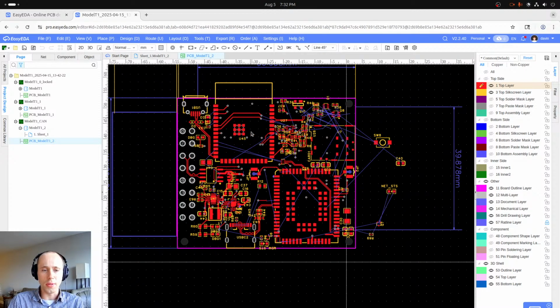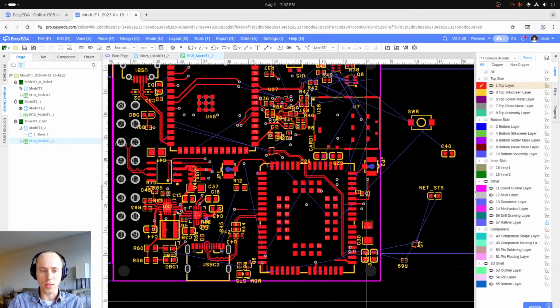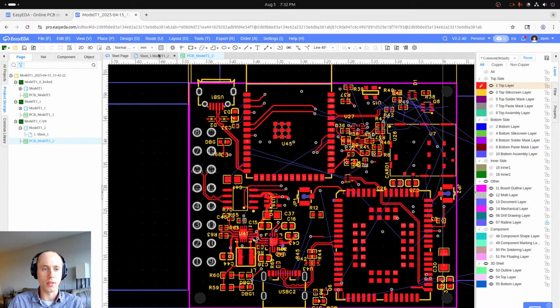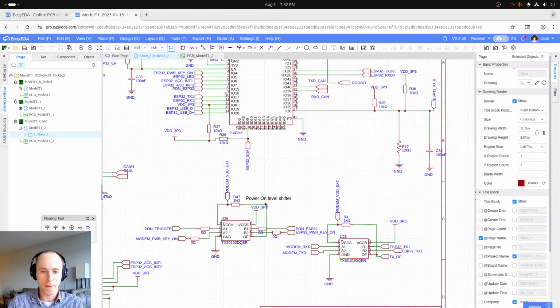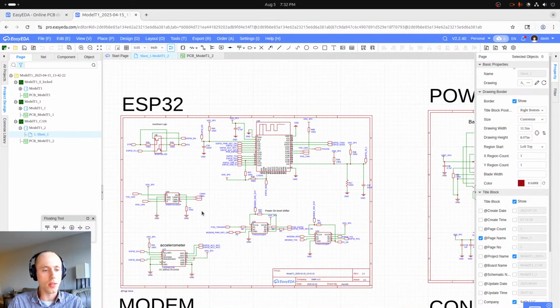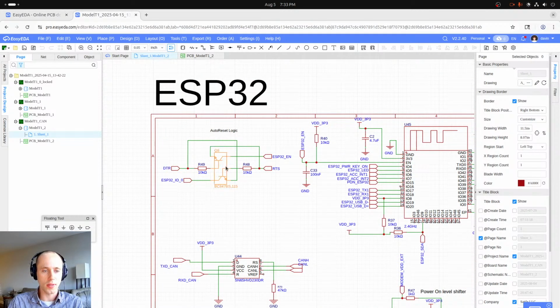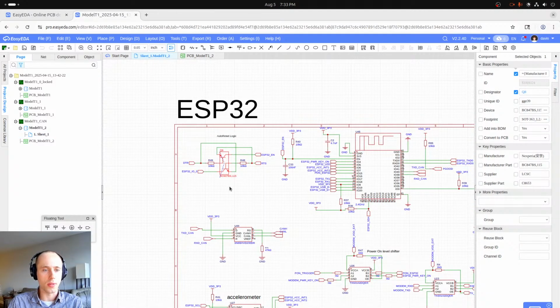I think for the main ICs, these are fine locations, and also the SIM card, so we're going to keep that. But it's all these other components, these passives and stuff, that we need to make sure are in the right spot in terms of proximity to pins. A lot of them don't really matter that much, but let's just make sure that we're on the right track. So I think we'll start with this component, Q8.